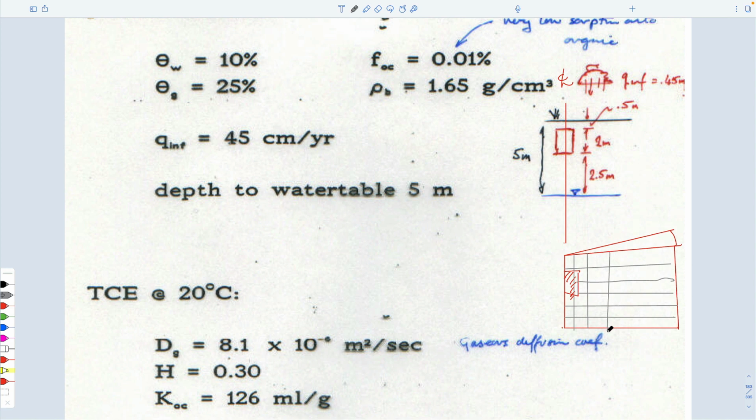Takes a long time to draw. I think I've got a picture somewhere else. And all this does is allow you to say, if you have this and you have rainfall washing down through this, what is the rate at which it would be dissolved from the bottom and then delivered to the aquifer? And what is the rate at which it would off-gas by vaporization outside, and maybe as a dense vapor also arrive at the water table? So this was aqueous, and this is dense vapor transport.